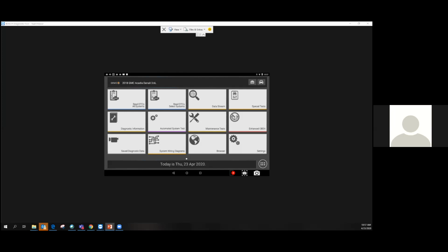That wants you to drive around vehicles, drive by signposts, guardrails. It wants you to actually be in a little bit of traffic because it's going to calibrate that radar while the vehicle is moving around. So basically one is going to require a test drive, and one is going to require the vehicle be parked with the designated targets from the OEMs.